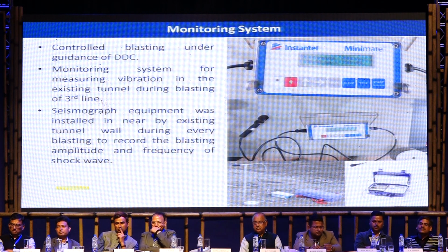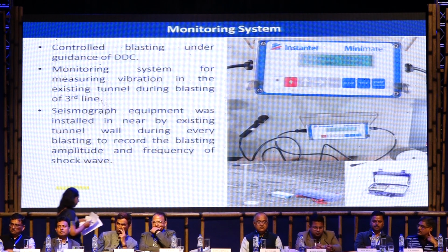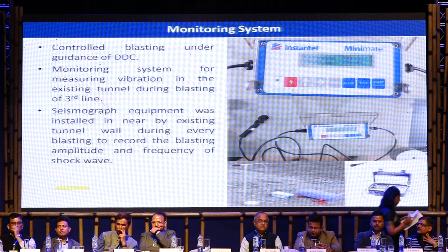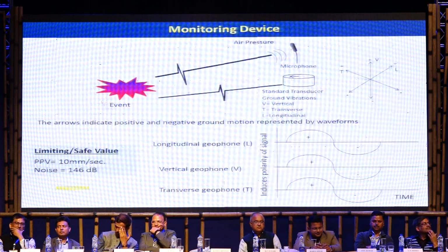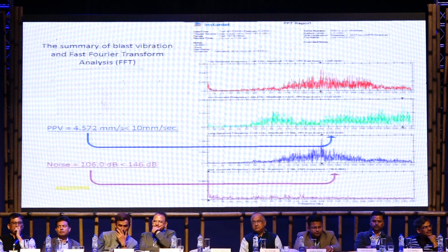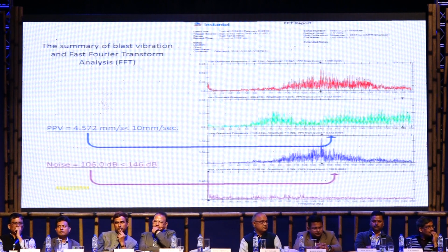When a blasting happens, shock gas is generated, and we divide the total blasting into 10 parts. You find that it is only a single blasting, but it is not a single blasting. It is a combination of 10 to 12 blastings in a very small millisecond gap. So a wave is generated, and its peak particle velocity is monitored by the monitoring system, a very small tool, and such types of signals are generated.